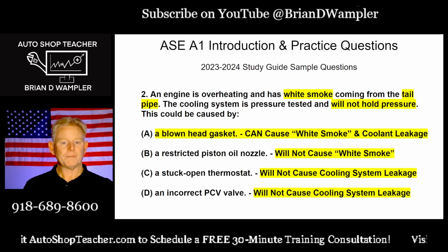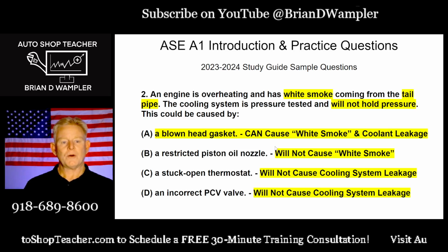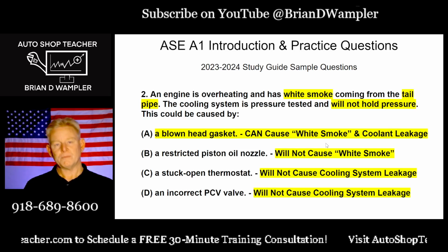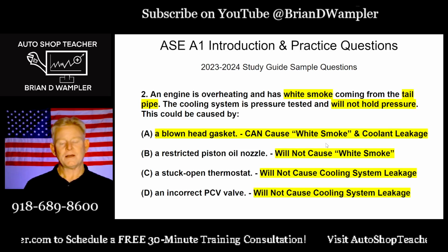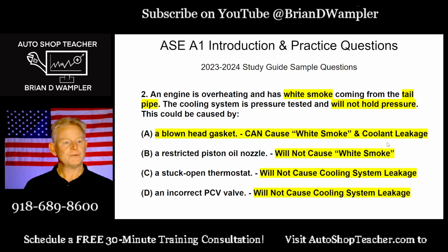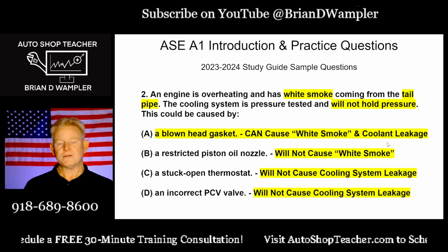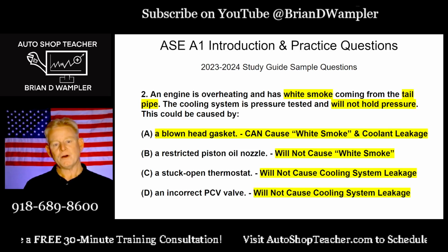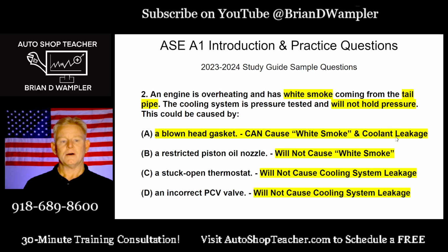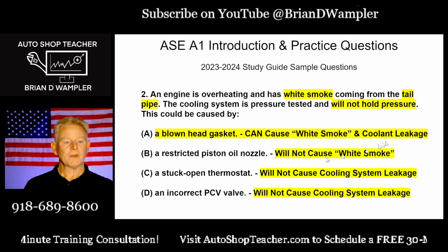All right, enough talk about smoke. Let's get back to our white smoke here. A blown head gasket can cause white smoke because of coolant entering that combustion process. And remember, we also have coolant leakage as one of our symptoms. So that's certainly the combination of the white smoke, and the coolant leakage could certainly lead to an overheating condition.